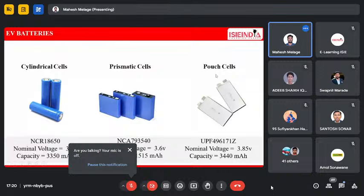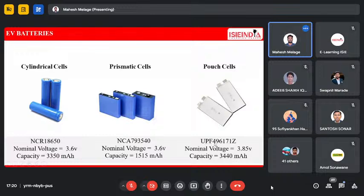Clear? Similar for the pouch cell, UPF 496171Z. This is the specification of a pouch cell. Similarly, the first two digits are the width, the second two digits are the length, and 71 is the height.